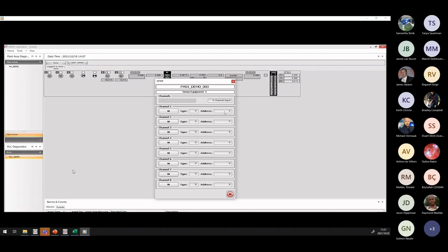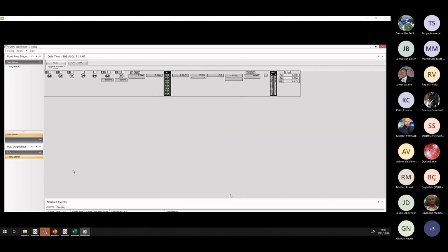Yeah, so I'm just running through a few of these to see what the availabilities are, what you can set. So this analog input one, for example, you can choose a different channel input module, because this one references a normal Mitsubishi analog input card. So you've got an 8 channel, you've got a 16 channel, so you can change those settings.